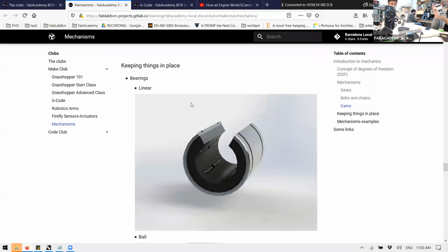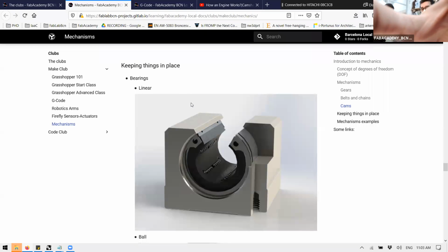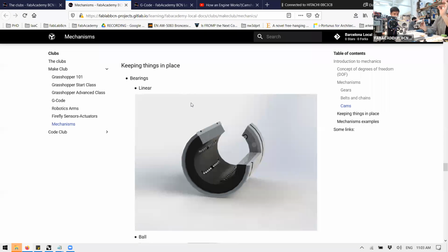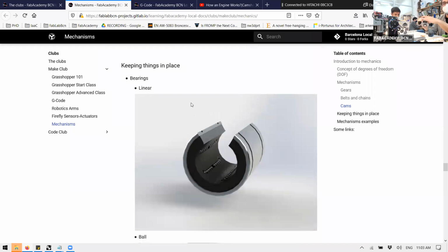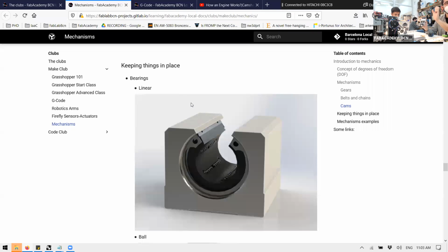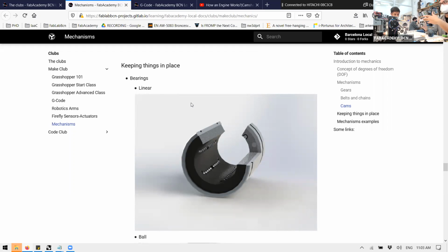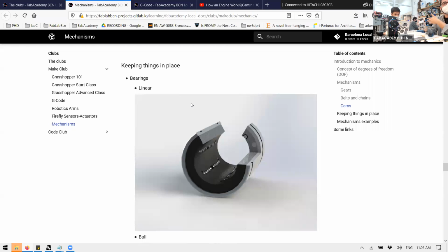The tighter the tolerances you have in your sliding elements, the smaller the movements you can create. Let's say, for example, the micro milling machine: all the pieces are really tight to each other to reduce the little movements that you might have. That increases the friction. So that means you are spending more energy in actually moving just the machine itself. That's why, for example, it's more difficult to cut stronger material with the small ones, because they are meant for accuracy.